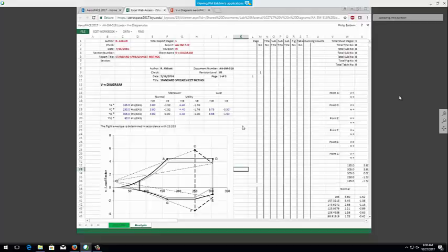So the relationship then can be to go through and do a different simulation. In this case, this is solving for the power loading such that the airplane goes to a minimum height of 3 feet. So I can go through and run that, launching at 6 feet of altitude at a velocity of 30 feet per second. Go through and solve the power loading such that the overall dip goes no lower than 3 feet, which was an arbitrary choice on my part, and in that case the power loading here is 22.7 watts per pound, which for a 10-pound aircraft means 227 watts is necessary. So a relatively straightforward model.